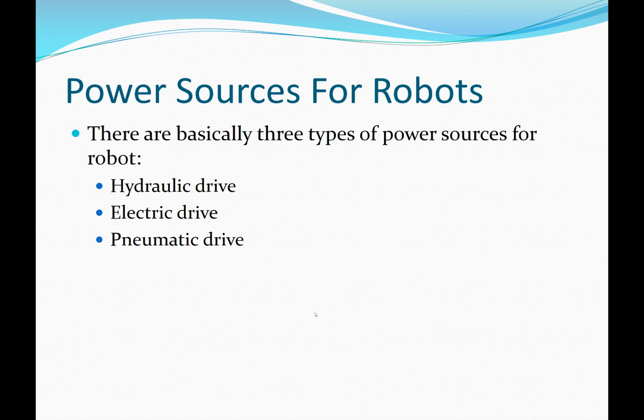You know, in the IC manufacturing area, you definitely don't want petroleum oil on your ICs before you start soldering the pins. And you definitely don't want electric motors anywhere near, because electronic ICs tend to not like static electricity. The transistor junctions and diode junctions tend to get zapped and fried, and the ICs don't work. So pneumatic drives are used in a lot of places.